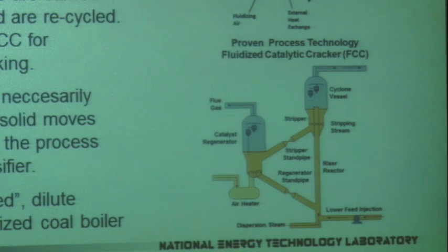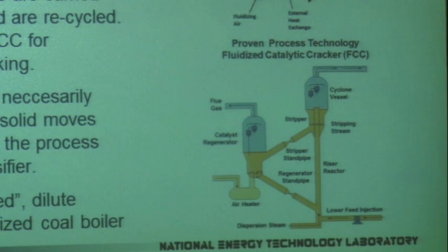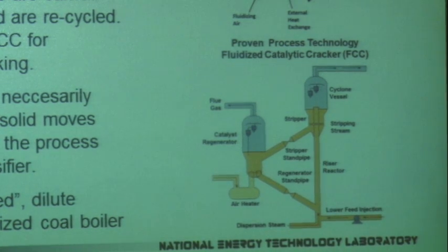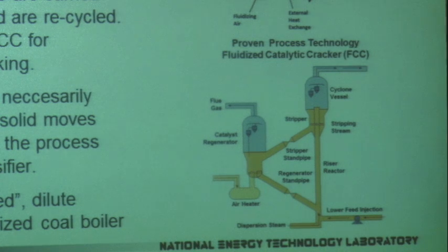But anyway, the idea there is you have very large particles and they move counter current to the gas flow, which is moving through that bed. And that has real advantages for chemical looping. I think Arnaud and I were talking about reactor design just a little bit ago. What that does is, for example in chemical looping, if you have the carrier raining down the top with gas coming up the bottom, you have fresh carrier, lots of oxygen, working up against that fuel which you're consuming from the bottom.